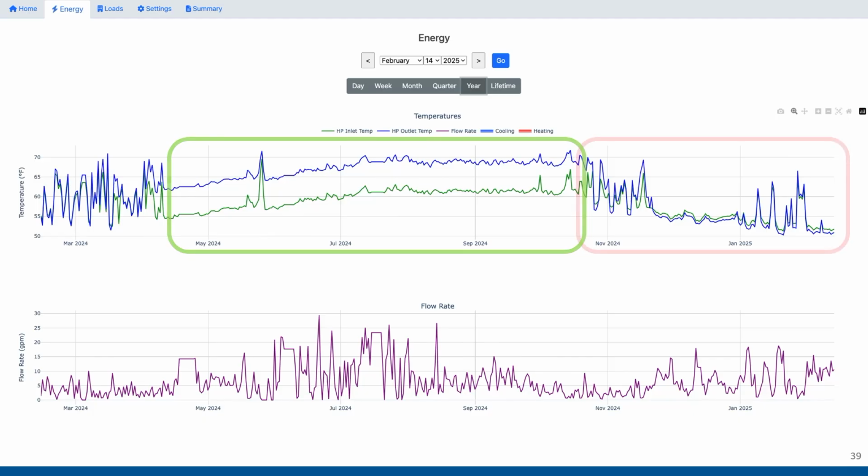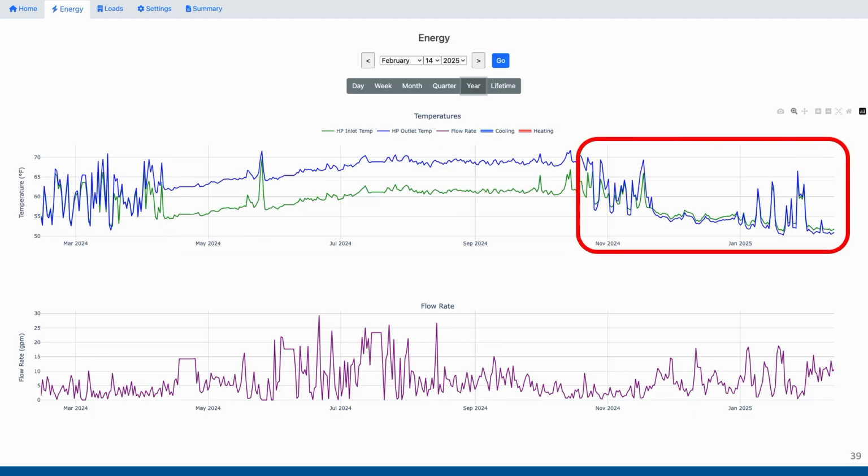So what happened on this one is each office had baseboard heaters, and they were manually controlled. And people would come in the wintertime and just crank their baseboard heaters in their office. And the ground source heat pump system, the water to air ground source heat pumps were on a separate thermostat, completely independent systems. The thermostats were in the hallways. And so those backup baseboard heaters, which are supposed to be backup, were heating and triggering that thermostat for the geothermal system to do cooling. So the systems were fighting each other.